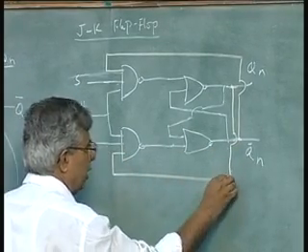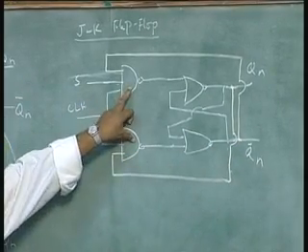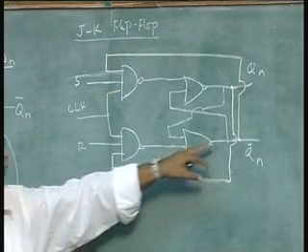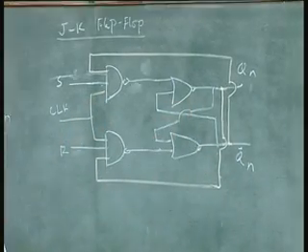That means I am making these 2 input NAND gates into 3 input NAND gates with an extra input derived from the feedback of the output of the flip flop.